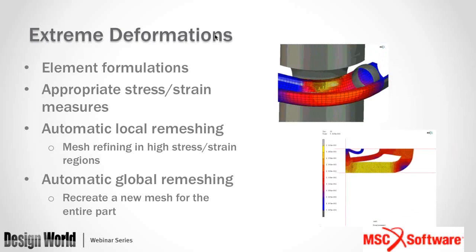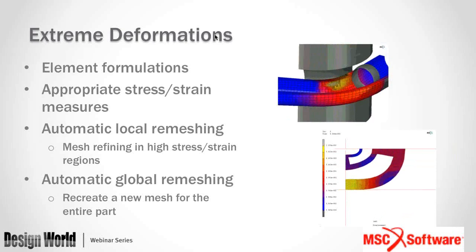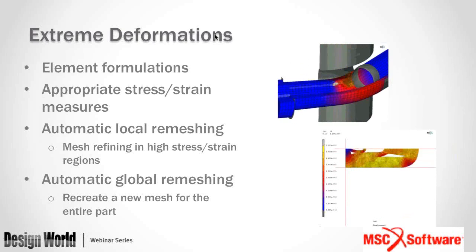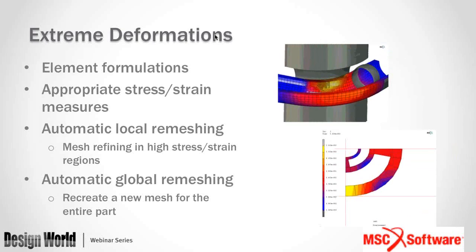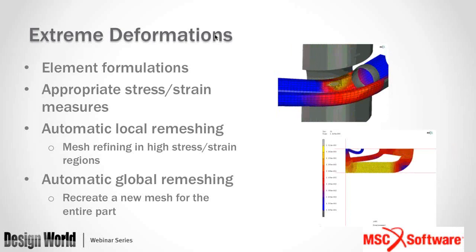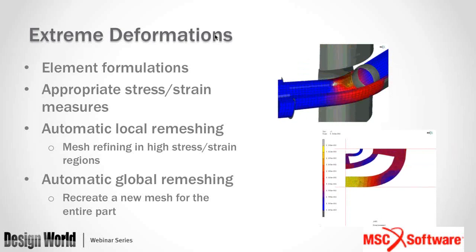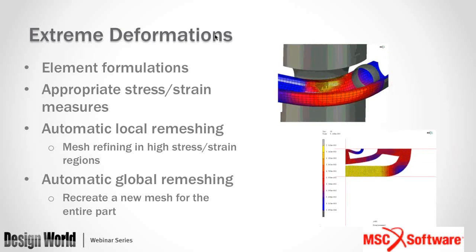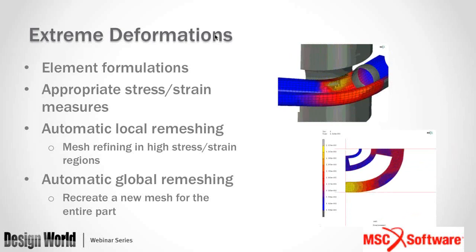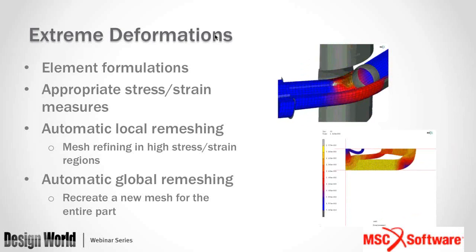First, you may not know where the actual high stress regions are in a component. So you can guess where the high stress would be and mesh accordingly. And of course, if you get it wrong, you would have to redo the analysis by readjusting the mesh. The other approach is to have a very fine mesh all along, but the problem is it can be very resource intensive and can take very long to run.